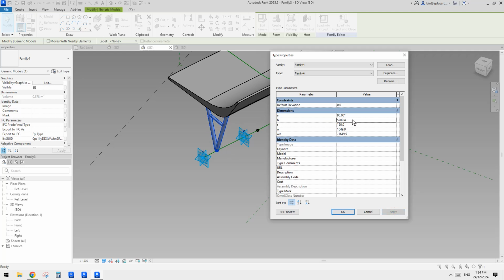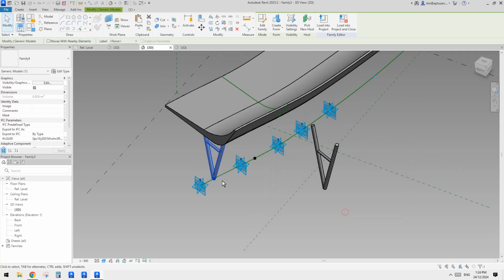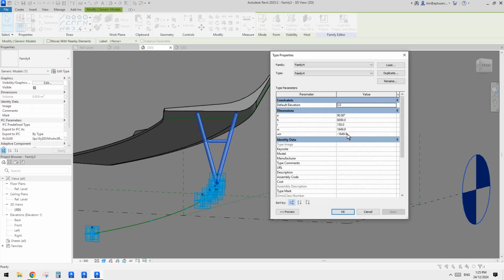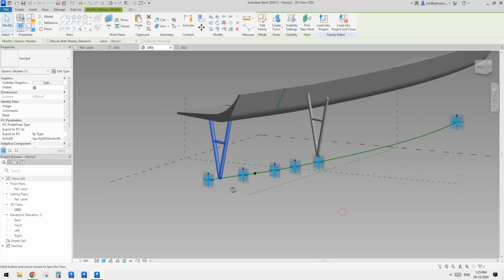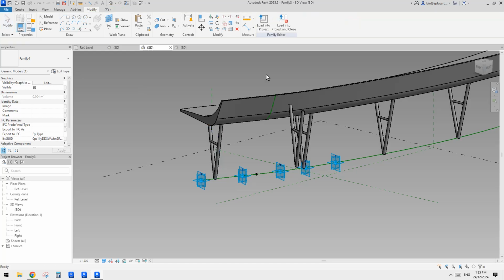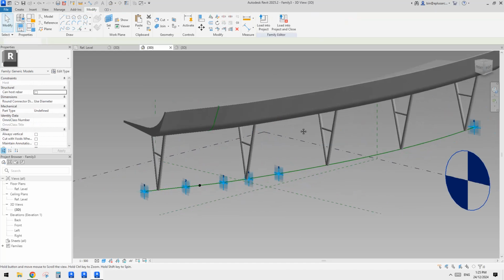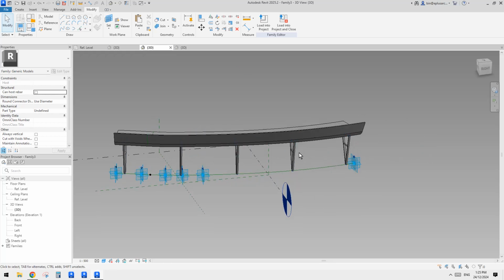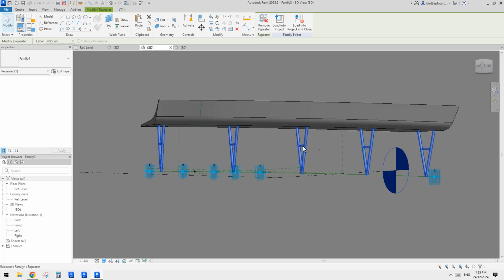Right, and also for the height, because we have this one at 6 meters, so we can just change this one to 6 meters. Everything else, all good. Width is between this and this middle point and here. I think it's okay. So 1.6, maybe 1.5 will be better. Okay, so now we can select this one and click on repeat, and it will be it. So you can see start from here 1.5 and here 1.5. So every maximum 12 meter.